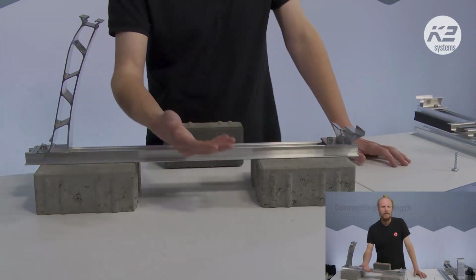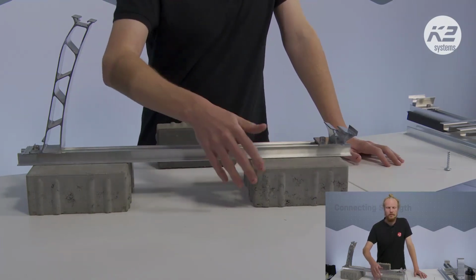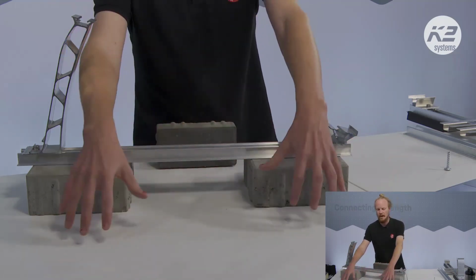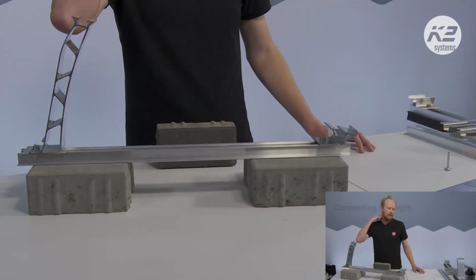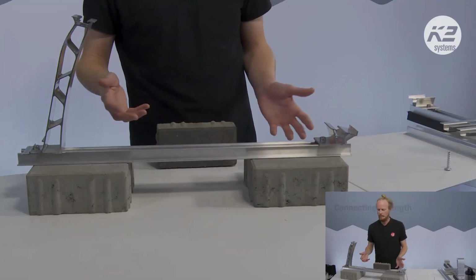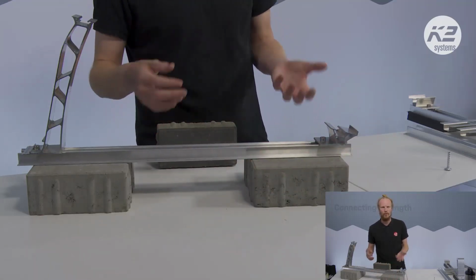If you have 5-10 centimeters of ballast, maybe even more, you can spread out the ballast a little bit, put this in, and then bring the ballast back around. And the gravel that's around the stones adds extra stability and support as well.